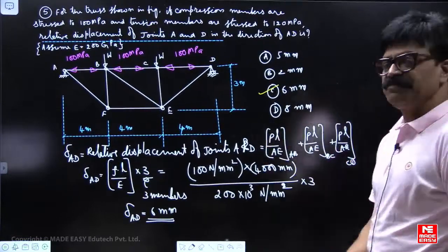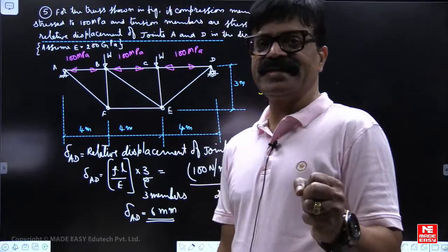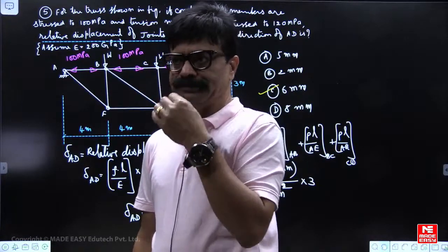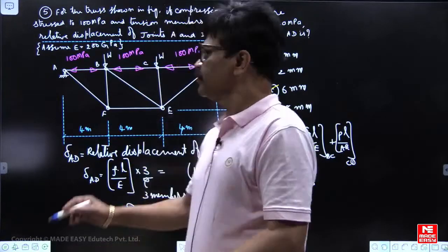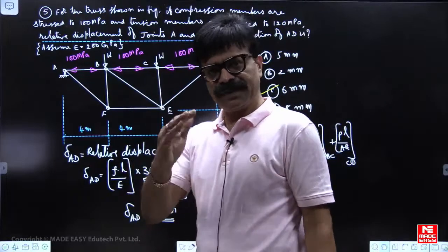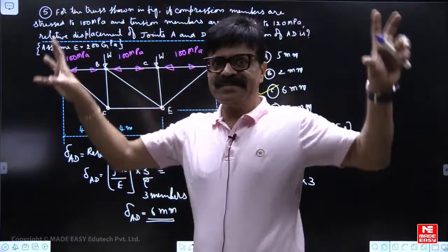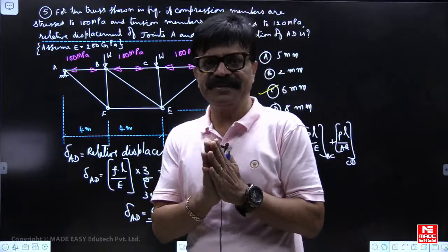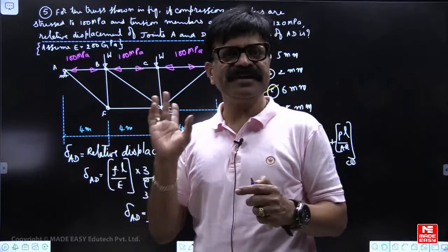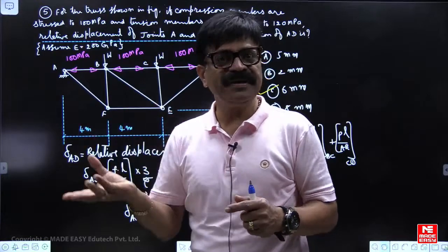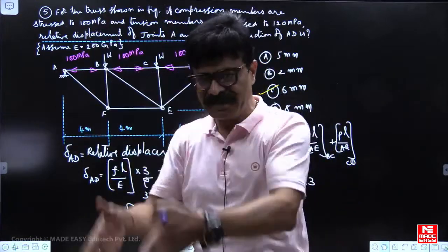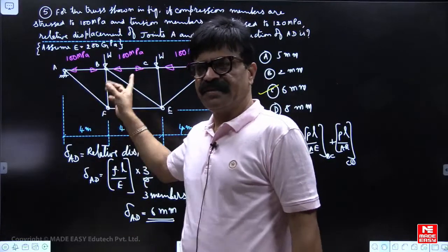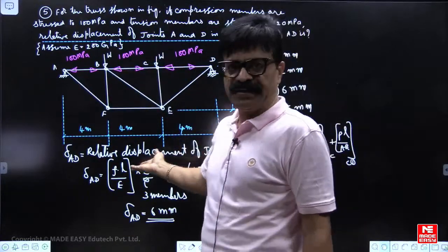So in 2 minutes our task is this much. First you have to understand the meaning of relative displacement and which topic it belongs to, and the allotted time is 1 to 1.5 minutes. With these constraints, you must think like this. In forces in the members of trusses, you must first count how many reactions are there, then how many are more than 3, so many times method of sections. Then the question becomes simple. In deflections, they will ask you relative displacement.